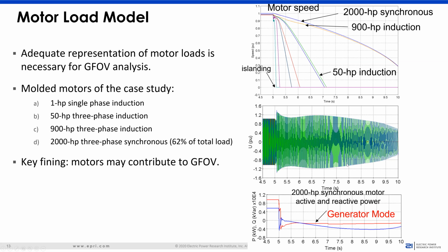But when there's a surge, the arrestor acts as a short circuit. So for switching surges and lightning impulse surges, the arrestor is operating in this region, and for rated voltages in this region. And in between, there is an operating region for temporary overvoltage, and the arrestors during ground fault overvoltage operate in this region.